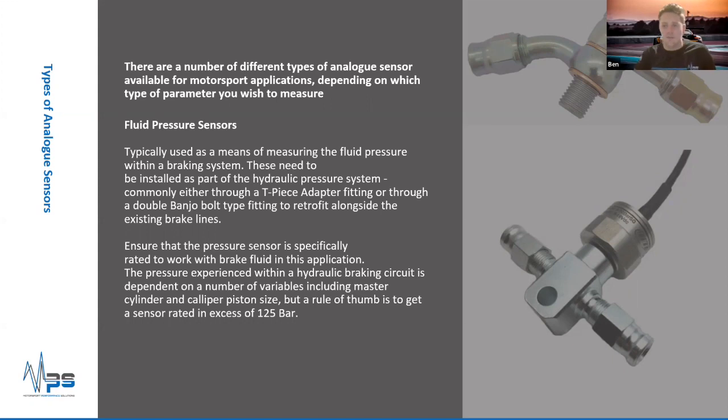So I really would advise, if you can afford to build it in as part of your brake monitoring, use a brake fluid pressure sensor. Just a few things of note. The hydraulic brake fluid can be corrosive to some types of sensors, so you have to make sure you buy one that's specifically approved for use with brake fluid. And you can see really high, or comparatively high, peak pressures in the braking system. So you want to make sure you've bought a sensor which is designed for that.